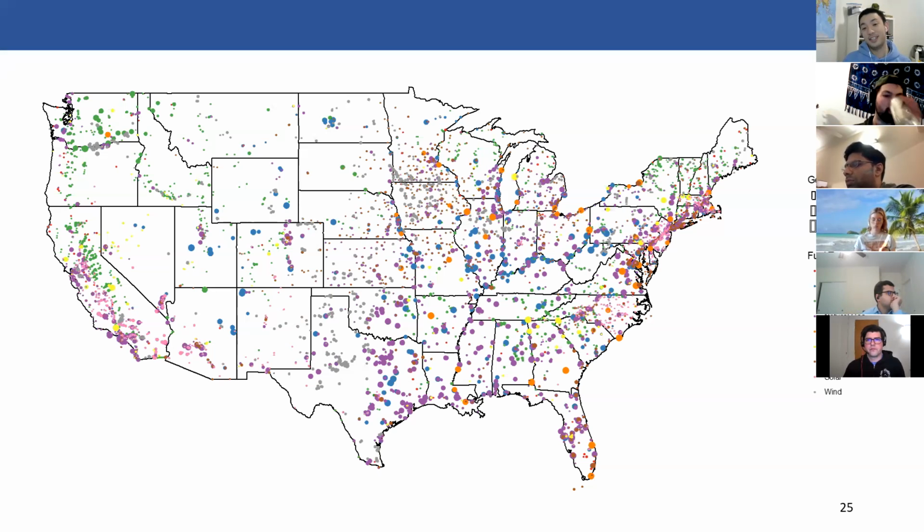And so your strategy is, okay, if I bid exactly the cost of my fuel, then at the worst, I will break even, right? But if I am not the last person on the dispatch order, then I can make a ton of money, or some money, right, in profit.